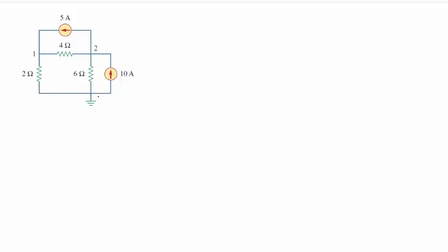I am going to somewhat arbitrarily call this node 0 down here. Node 0, voltage at 0 is 0. That was my reference point that I decided. I'm going to go through and find all the nodes. There's a node at 1, here's a node at 2, there's 3 nodes, 1, 2, 3, but one of them is at 0, so I have 2 nodes where I don't know the voltage, 2 nodes and 2 unknowns. I'm going to have to write 2 nodal equations. So we're doing nodal analysis, KCL at node 1.